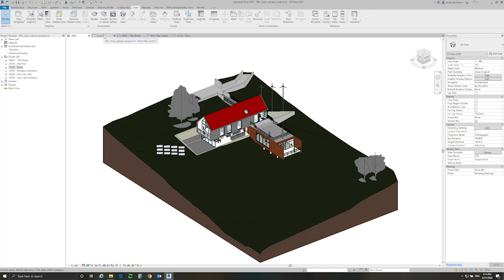One thing I want to mention on this too is if you have multiple Revit projects open, or Revit models open, if you will, they're also going to show up as tabs here. And the name of your tab, you'll notice it says Level 1. If I had another Revit project, it probably has a Level 1 too. So sometimes it can be difficult to tell which Level 1 that's pertaining to if I had like a second building open. It can be helpful to just hover over it, and you can actually see that it has the name of the project and then a hyphen and the actual name of the view that you're in, whether it be a 3D view, sheet, etc. So that can be pretty useful right there.